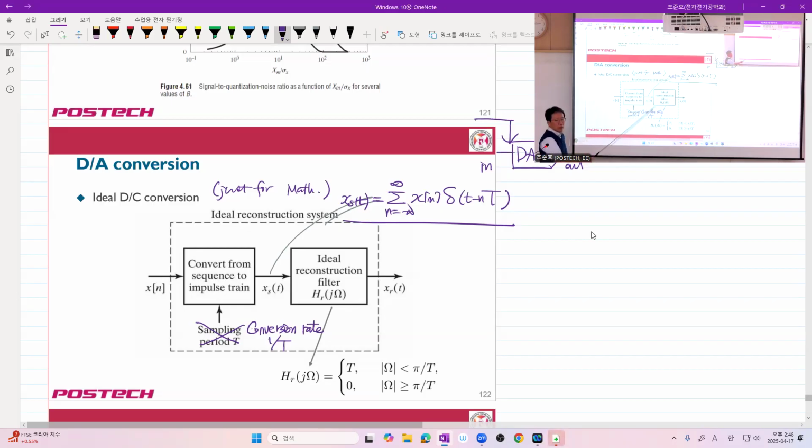And then here goes our interpolation or reconstruction filter. And here is our reconstructed signal, which could be the same as, or a lot or a little bit different from, our original continuous time or desired signal. Be careful, as I told you, even though our textbook says sampling period capital T and sampling rate 1 over capital T, most of the specifications from our industry, such as Japanese companies' ADC and DAC specs, or Texas Instruments or Analog Devices DAC specs, usually talk about conversion rate, got it? When they have a D to A converter, the conversion rate is 1 over capital T.